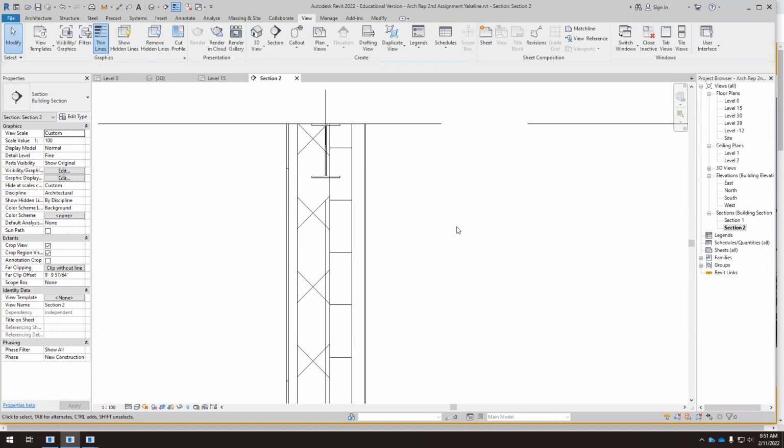Okay. So what would I do? I would make the thermal insulation a continuous thermal insulation that covers the steel column and the steel beam.